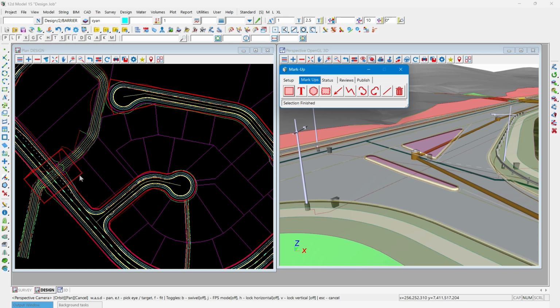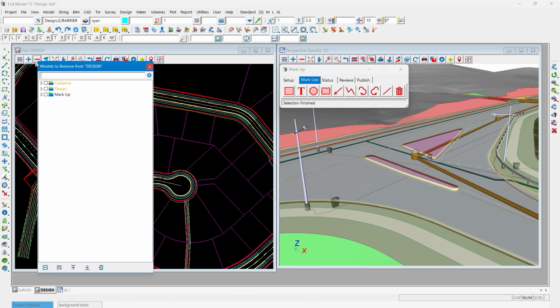And as soon as I produce my first markup, the tracking starts. So the model names is the first place you can start tracking who did it, when and where. So if I go to the model list that's been produced, I have a markup object tree group with a markups subgroup, and then as the markups run through different particular dates, it'll automatically put the system date and the username of the person that has produced that markup. So that's the first start of the tracking.